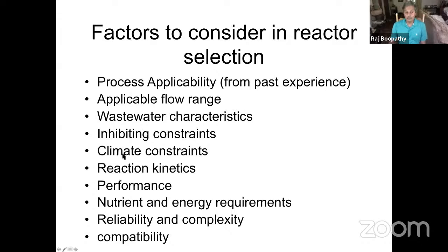And then, of course, in Indonesia, it may not be applicable, but in other places there is a temperature issue. If it is a cold country, cold zone, during the winter months you are going to have a performance problem if the temperature is too cold. And then climate, and then we also have to do the reaction kinetics: what's going in, what's coming out, at what rate it is being removed, make the calculation, and do the performance analysis of the reactor. You also need to know the bacteria; if there are some nutrients missing, you may have to provide nutrients to make the bacteria happy. And then, of course, you need to calculate how much energy you're going to use to operate the reactor.